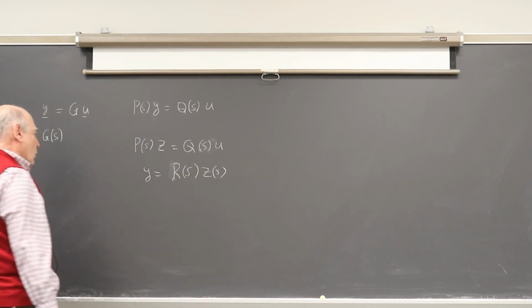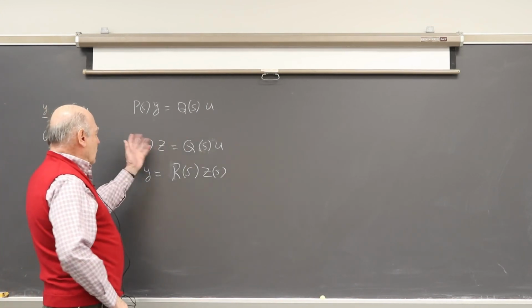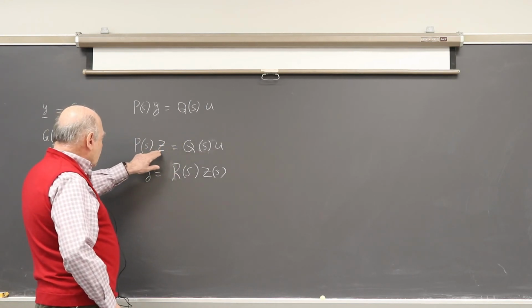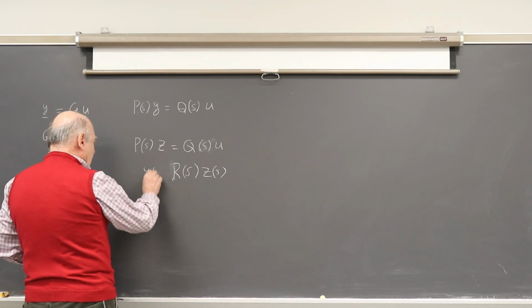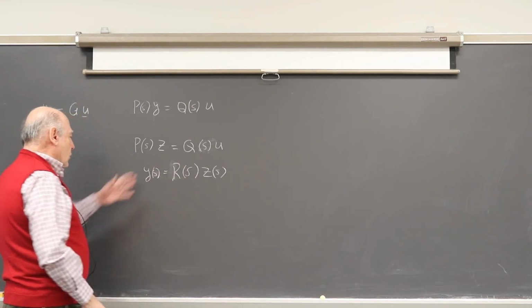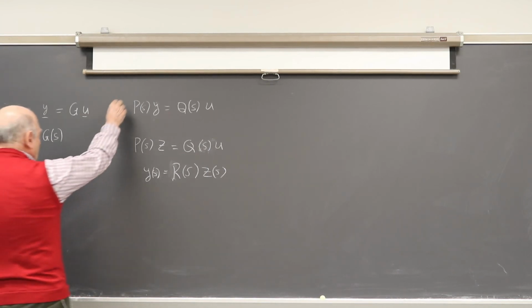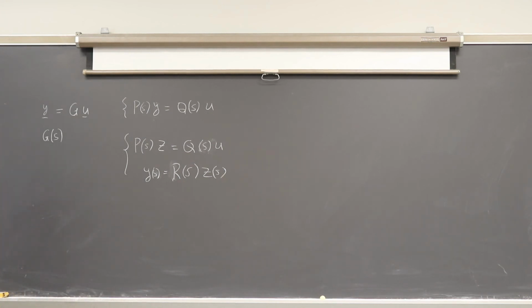This is called the pseudo state representation because this equation sort of resembles the state equations, and this variable xi will determine the output in the frequency domain in a linear fashion through a matrix R. So these will be the two basic cases that we will deal with in multivariable linear systems.